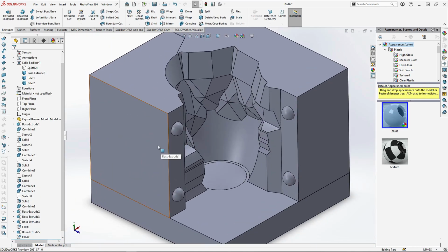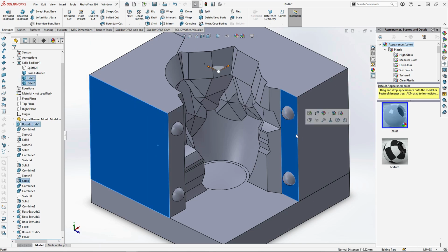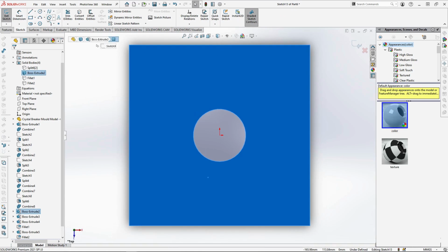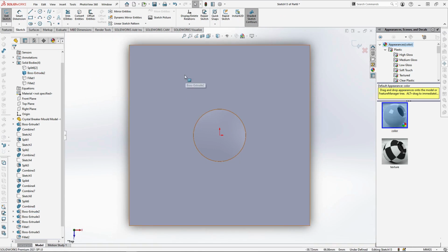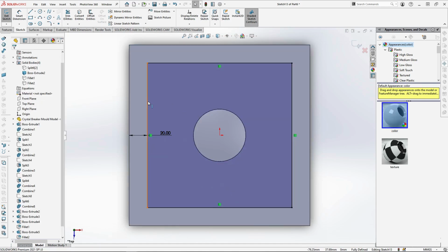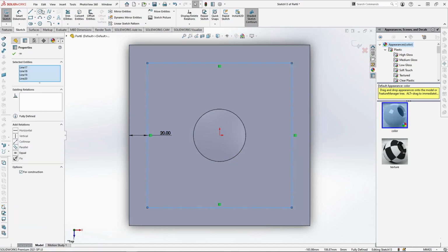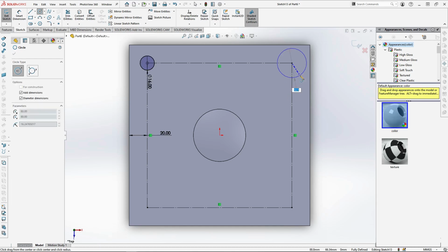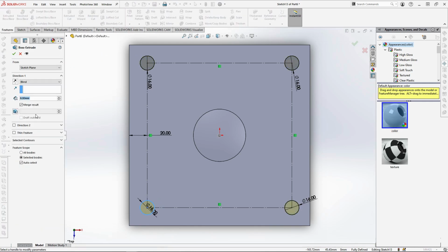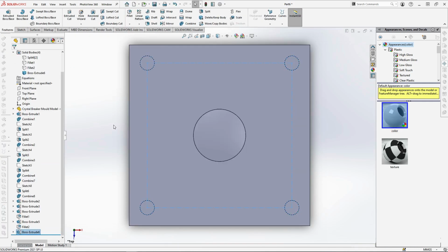Finally, to add notches to the base part, hide all the top mould parts. Start a sketch onto the top face and offset the face 20mm inwards. Then make the sketch for construction. Use this to add 16mm circles onto each corner of the square. Extrude the notches by 8mm again, merging only to the base piece. Ensure you fillet all the notches by 8mm.